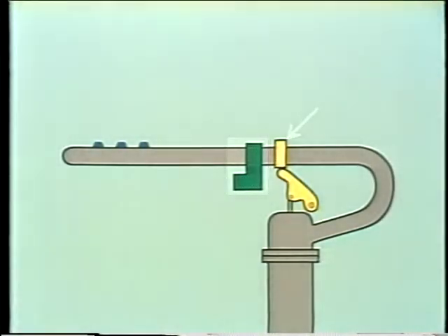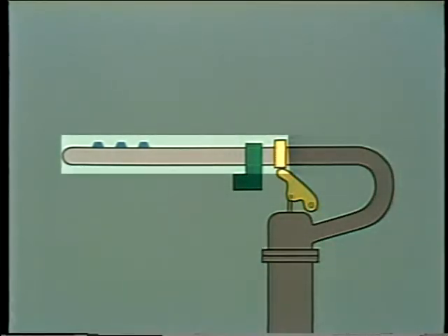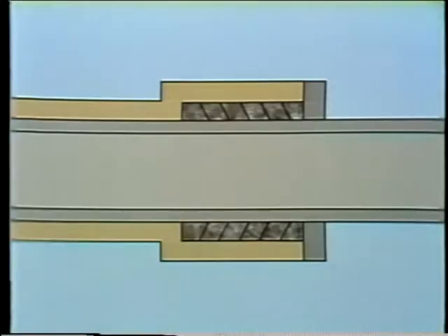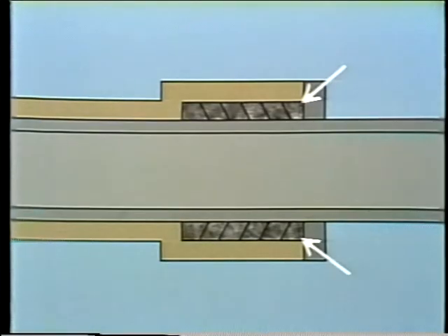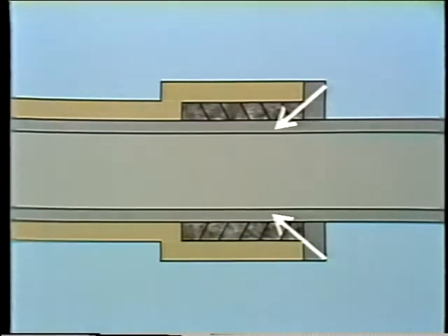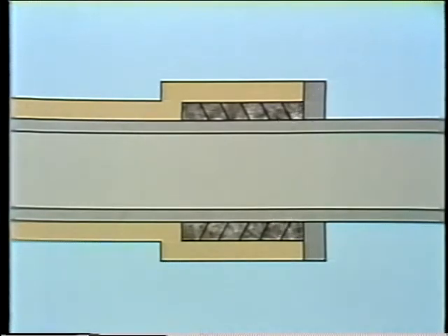We'll look at a way this cam arrangement typically works in just a moment when we examine short tube retractable soot blowers. In addition to the drive mechanism and valve trigger, another major difference between fixed and rotating types of soot blowers is the way the rotating element is sealed. This is done to minimize leakage of the blowing medium. Packing, similar to valve packing, is used between the element and the feed tube. This is also typical on retractable soot blowers.